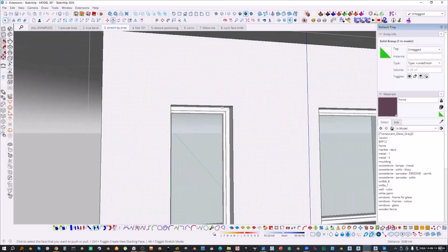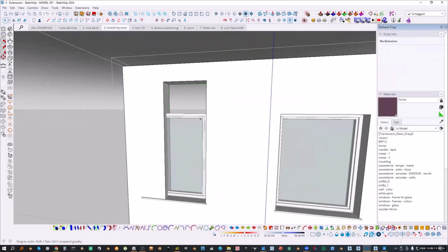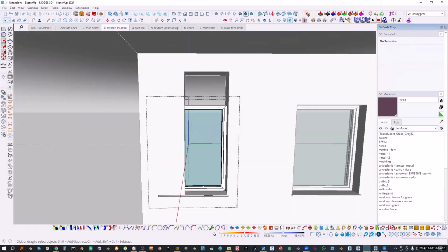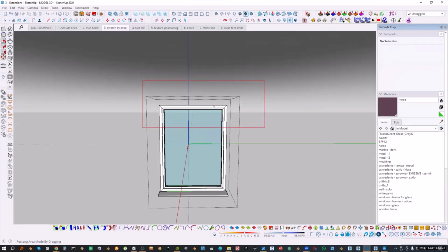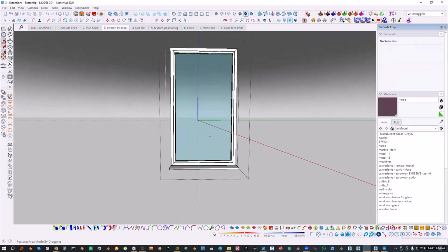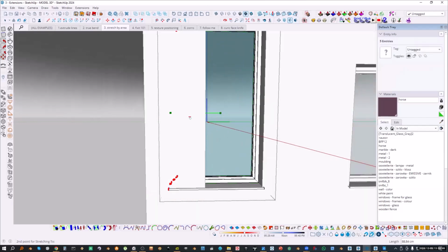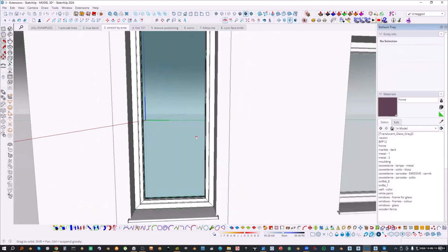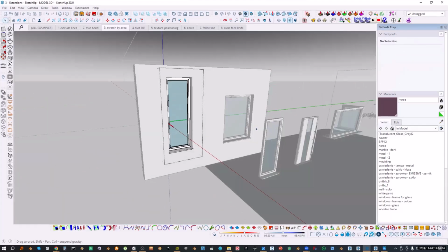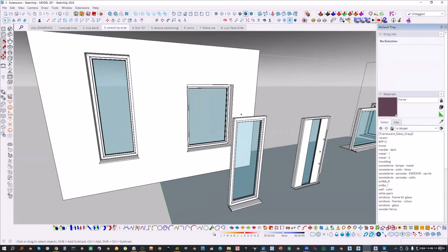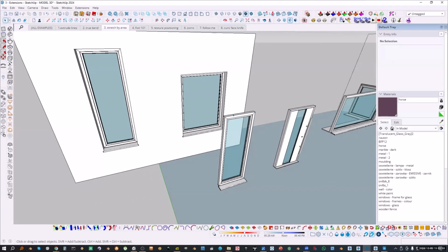And let's say I want that window to be higher. Obviously, it won't look good, but it's just an example. So now again, I'm going to select the top, click again, and here the side, click. I can hold Shift to lock the axis, the green axis this time, click, and now it's done. And basically, before I discovered that plugin, I was doing it manually, one piece after another.